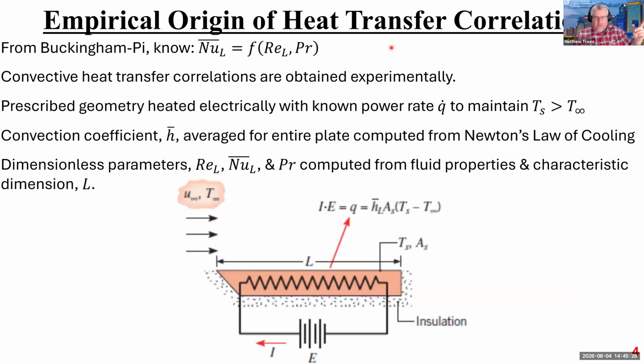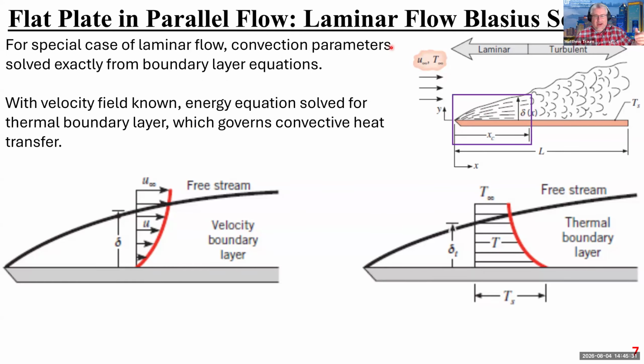And just like I said, with our list, remember our list, repeat silently to yourself: all the action is in the boundary layer. All of the heat transfer associated with flow over a flat plate happens in the boundary layer. So the boundary layer on the laminar side grows, and we call the laminar boundary layer height delta. So delta is growing with X. And then there's also a turbulent boundary layer, which also grows with X, and that's called delta sub T. Those two basically get stitched together at this critical value of X. So we'll get into that when we talk about turbulent flow. For now, we're going to talk about laminar flow, which is why I have boxed the first part of this flow field to remind me to focus on that.